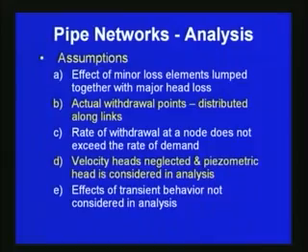So, as we have seen, the major challenges here are that we do not know exactly the direction of flow, and even from time to time the direction may change. Also, since there are a number of pipes, a number of fittings will be there. So, all these losses we have to consider, and then we also have to see that the continuity equation and the energy equation are satisfied at all nodes, and we have to consider these equations with respect to loops also.